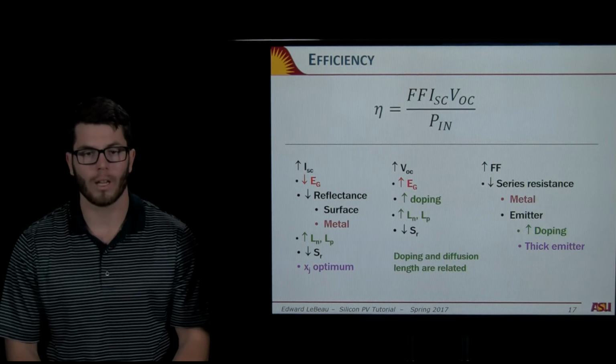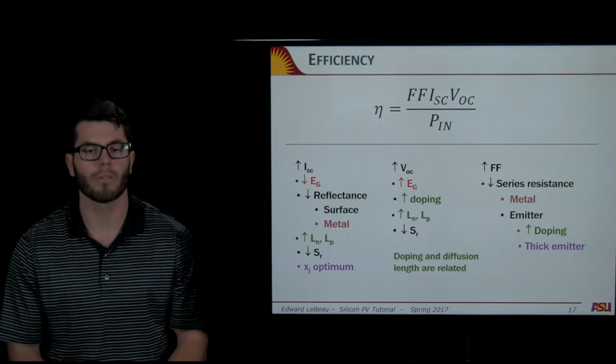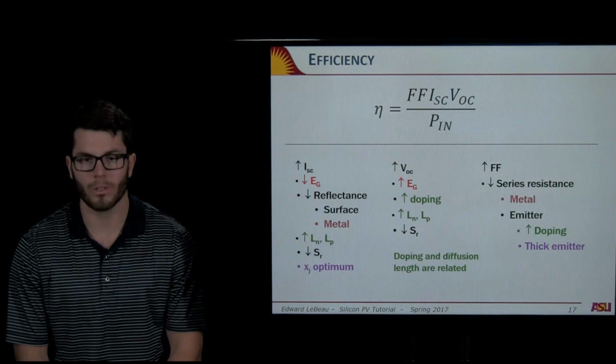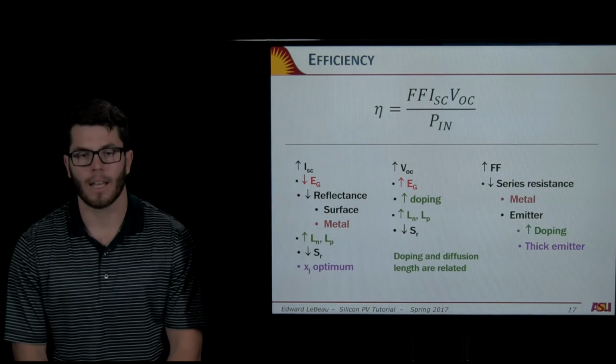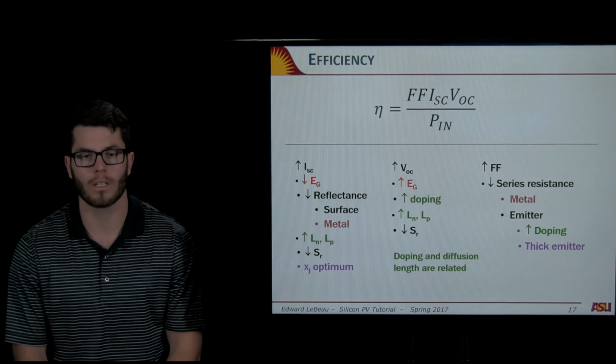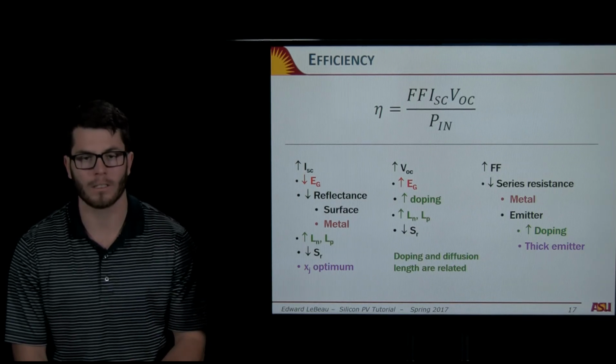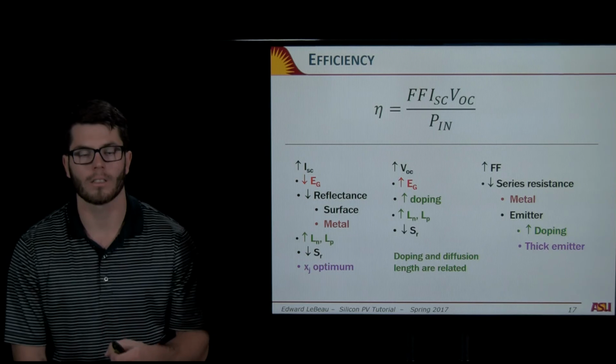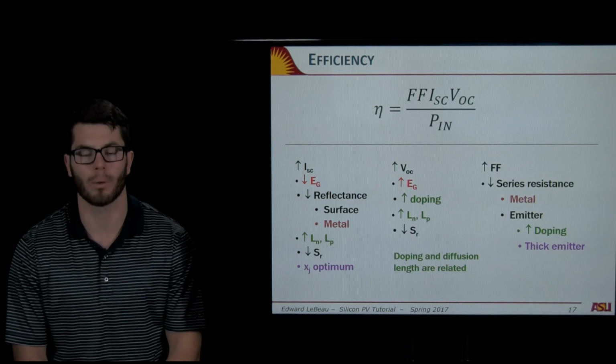And then what do we do to increase our fill factor? The big thing, reduce your series resistance. Your series resistance has to get down. That has the biggest effect on your fill factor. So again, let's take a look at that equation. Efficiency is your fill factor times your short circuit current times your open circuit voltage over the input power.